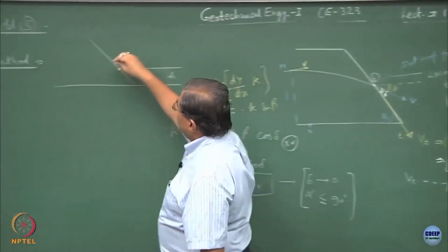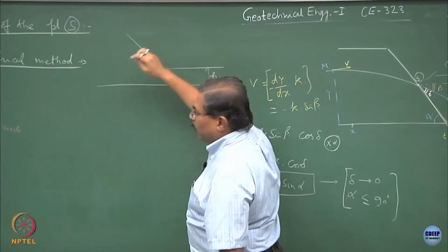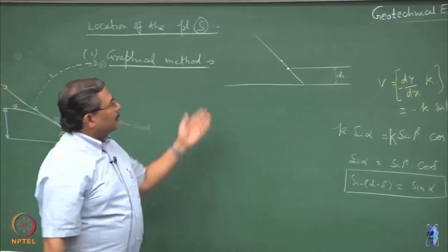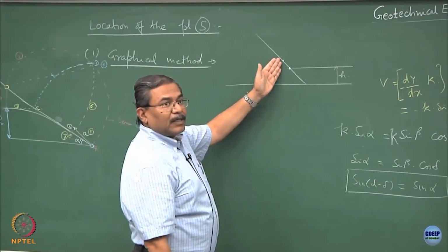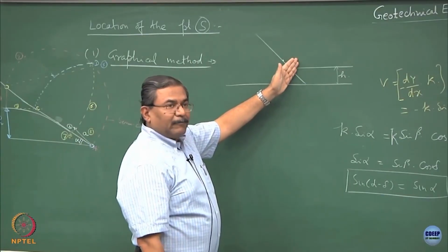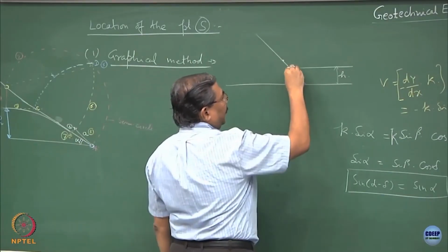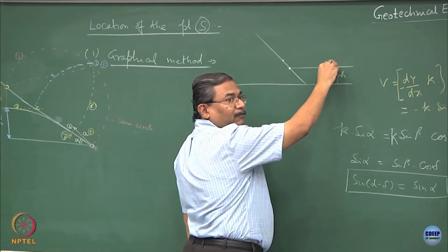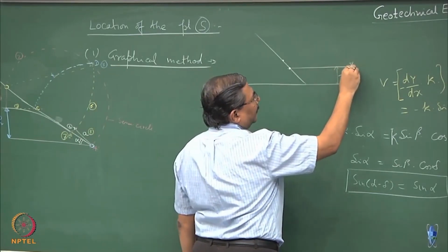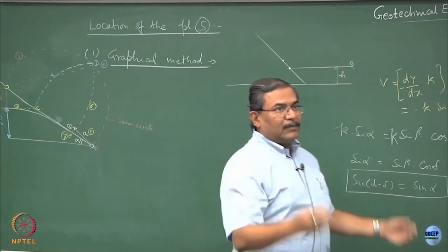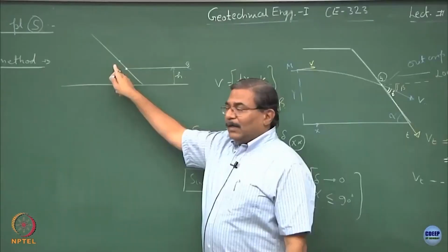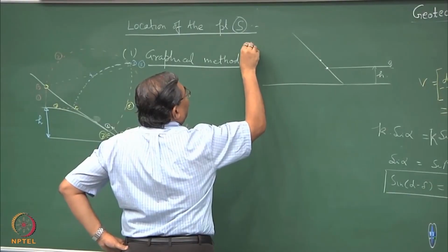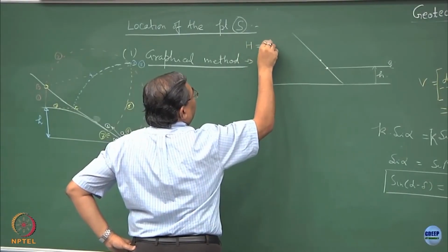If this point S is lying somewhere over here, this is going to be more damaging to the body of the dam. You understand? Because the seepage line is coming and hitting it over here, so the erosion will start here. So, the better way would be, let this point remain submerged into the water table, clear. This is one of the ways, and I can create a reservoir here where I can allow people to do some amusement or whatever. So, I am sure you must have realized what we are trying to do is, we are trying to relate H and H, alright.